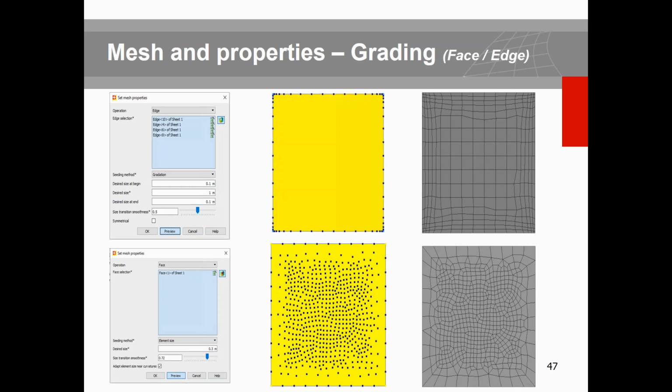And you can combine all these effects to make sure that your model is optimized with respect to the mesh topology and analysis time, because if you define fine elements all over the model while there is no need to have such a high density of elements, that's going to cost you time in terms of running the analysis. Therefore, you can always rearrange the position of these elements in the corners and the zones that are more often subjected to the construction or some, say, loading or manipulations.